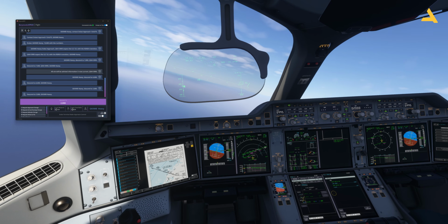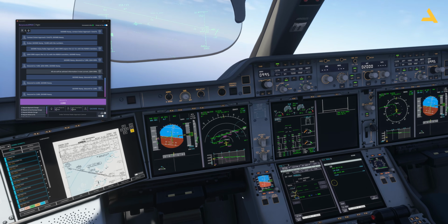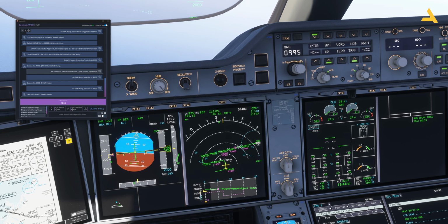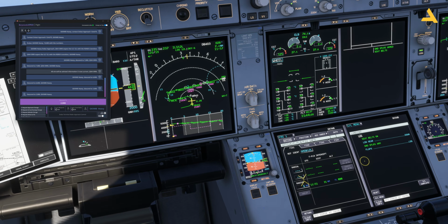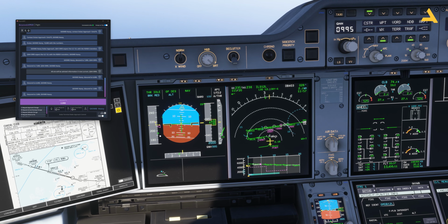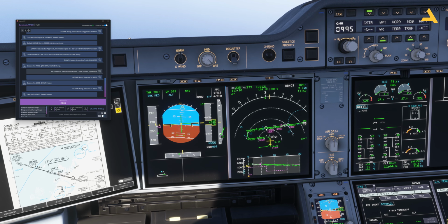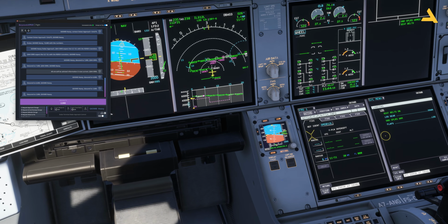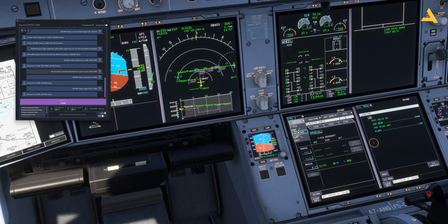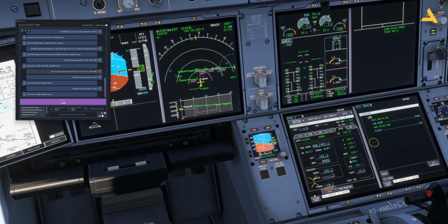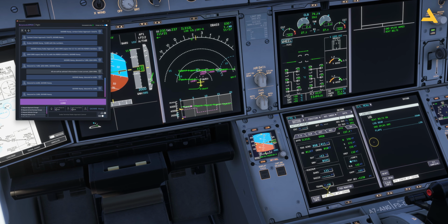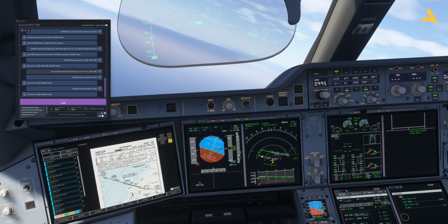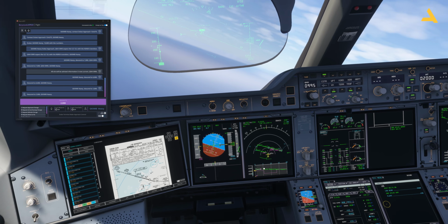That's it. Now with this I can activate approach as well, because I'm now near the runway, and at this point my speed should not be more than 185 knots. So once I activate approach, the speed will not go less than this point, the green dot speed, and then just before this point I will start extending the flap so that the speed is reduced. So let's go to performance, approach, and activate approach, confirm, and that's it. Now let's wait for the plane to reach this point, then I will just take you from there.